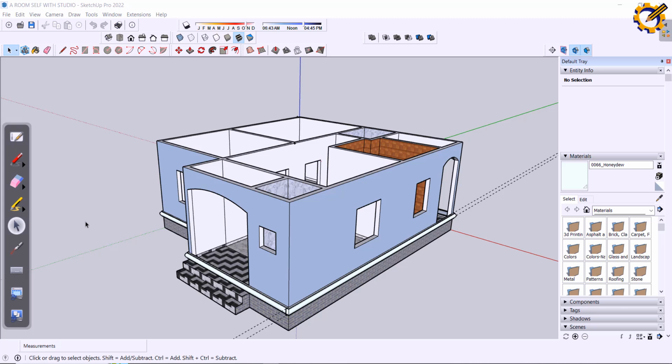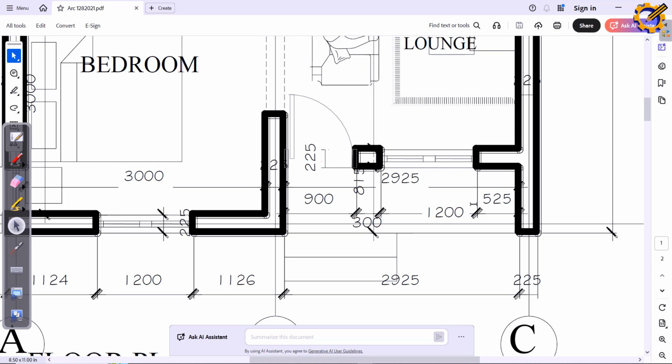So you need a column vertically, a beam sitting on the column, then a slab can now sit on it. And that is what actually makes those structures possible, that you have first floor, second floor, third floor without a wall. So it is the column and the beam that carry the load in such a scenario. You get it now? And that is what we have here on the building plan. This is how they represent it.